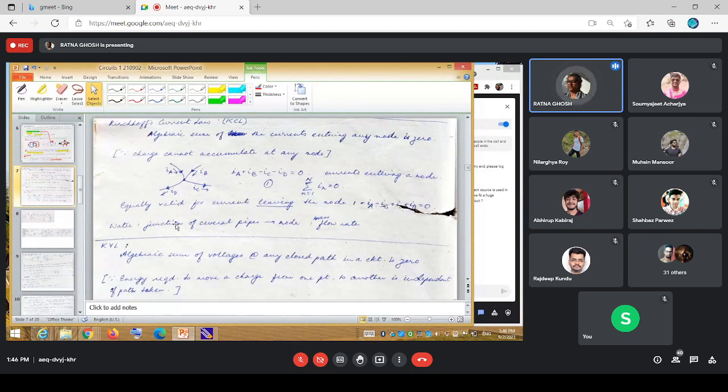And this is something that I mentioned earlier: mass flow rate in a hydraulic system is equivalent to charge flow rate, or current, in an electrical system. So the through variable in a hydraulic flow system, the mass flow rate, is equivalent to current.